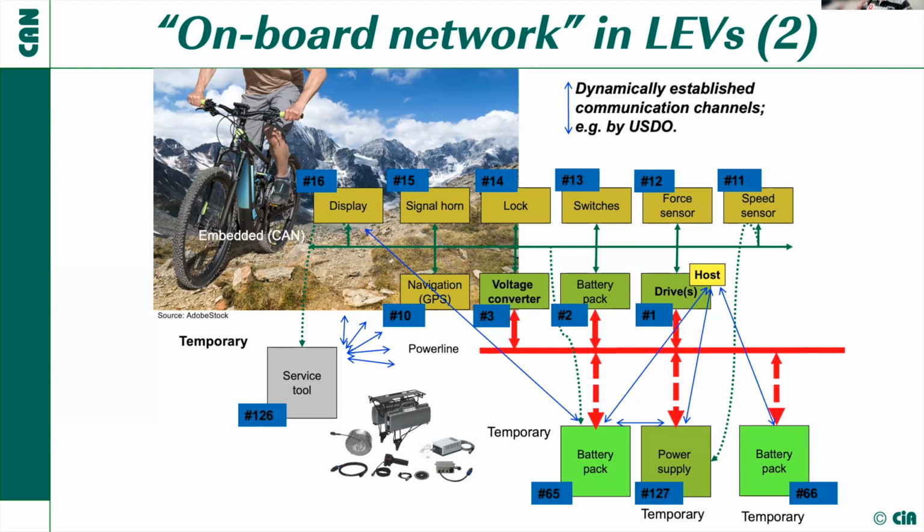We have learned already by my talk or by Torsten's talk that we have the possibility to establish dynamical cross communication. And this means also for new devices, I can access these devices, read out their object dictionary, learn about their origin, their functionality, and can embed them as a host controller dynamically into the system. Or I can even make some assessments whether they are even allowed to be present in the system at all.